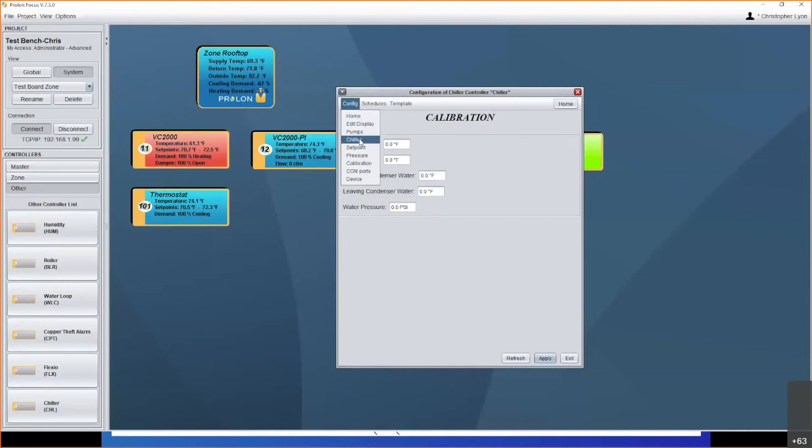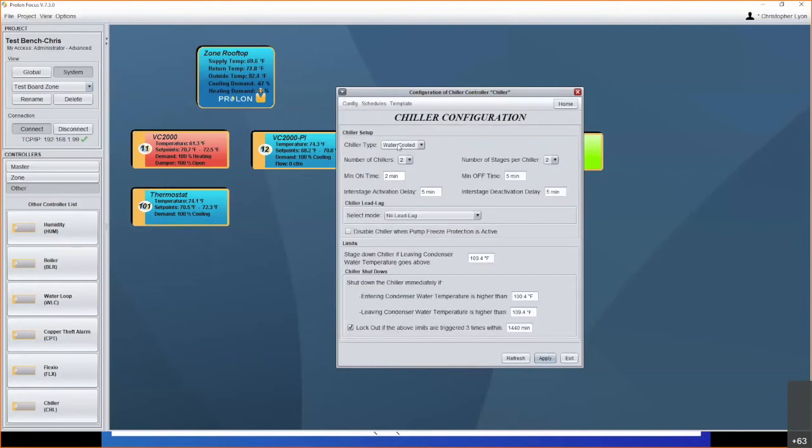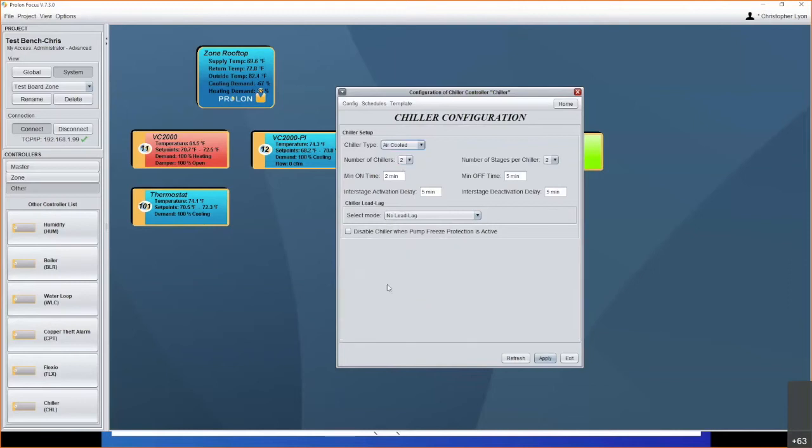So we've looked at the water-cooled chiller, but if we change over to air-cooled here, a lot of this safety goes away because typically an air-cooled chiller is going to have all of its own integrated safeties because it's a package unit. It's not necessarily relying on other equipment to provide a suitable heat rejection source for it.